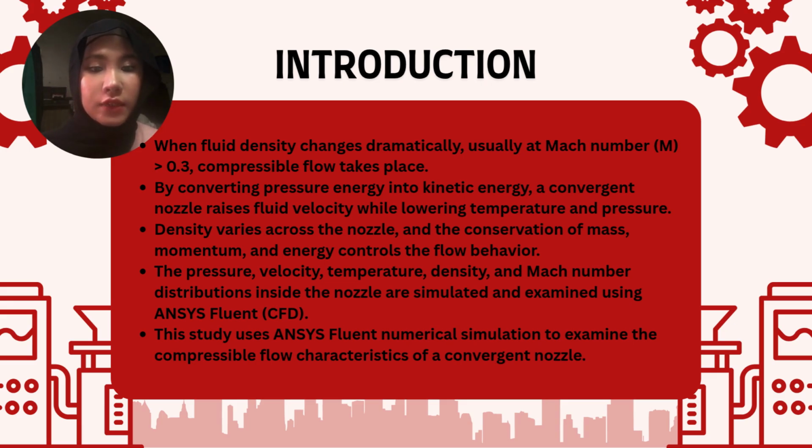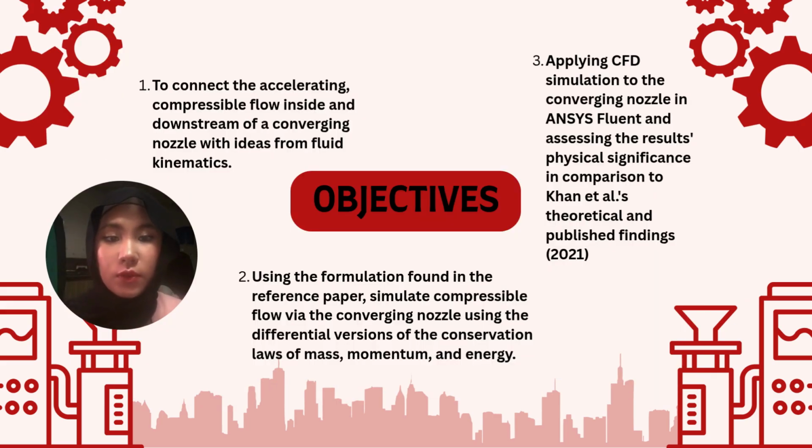In this study, ANSYS Fluent and CFD were used to simulate and analyze the pressure, velocity and density distribution to better understand the compressible flow characteristics of the nozzle. For our objectives, the first one is to connect the accelerating compressible flow inside and downstream of a converging nozzle with ideas from fluid kinematics. Second, using the formulation found in the reference paper, simulate compressible flow via the converging nozzle using the differential versions of the conservation laws of mass, momentum, and energy. And the last one is to apply the CFD simulation to the converging nozzle in ANSYS Fluent.